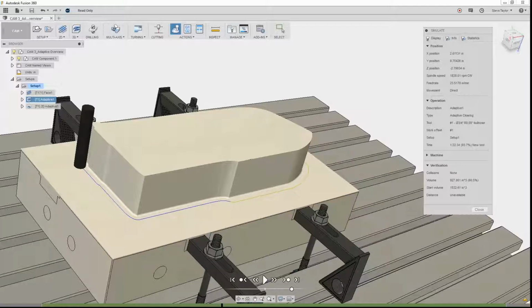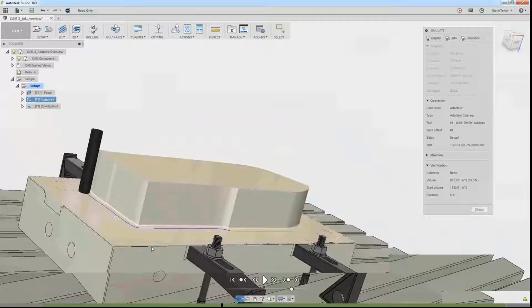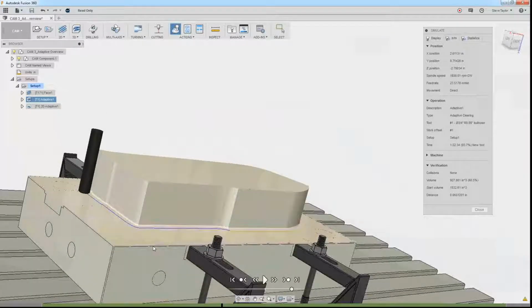You can see we set a maximum of 80% of the flute length, which, you know, we're not near there. So there's a lot more of the flute length left, but as you're looking at it, you can see we're using it to as much as we can, the depth. If we zoom in, you can see a black line. So if we actually look here, that black line there, that is actually our finished model size.